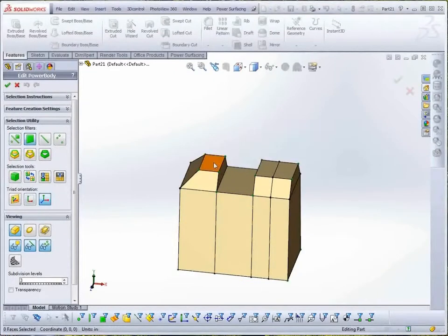Now I'll switch to Select Face mode while I make the handle. I want the front of my handle to flow back from the spout, so I'll extrude using the A key and rotate the top face a bit. Then, using the local coordinate system, I'll scale it in a little and then extrude again. Next, I'll extrude the back piece to match.